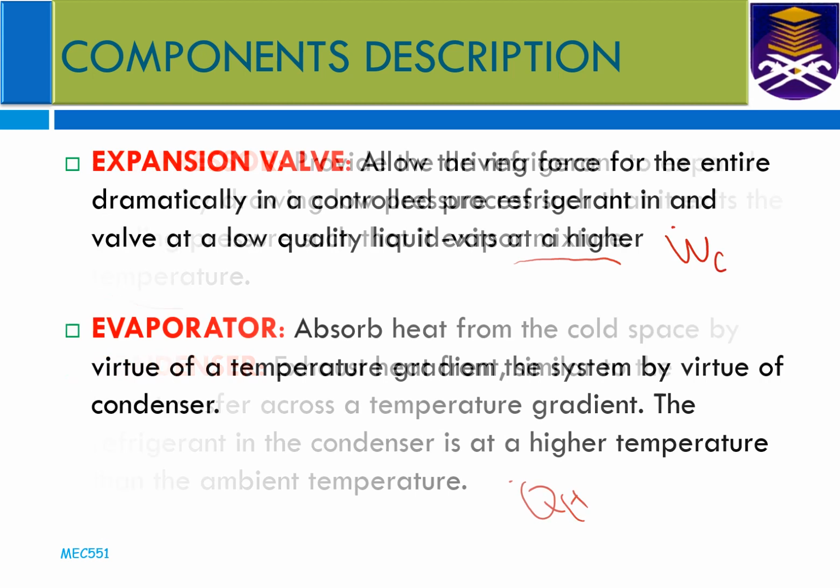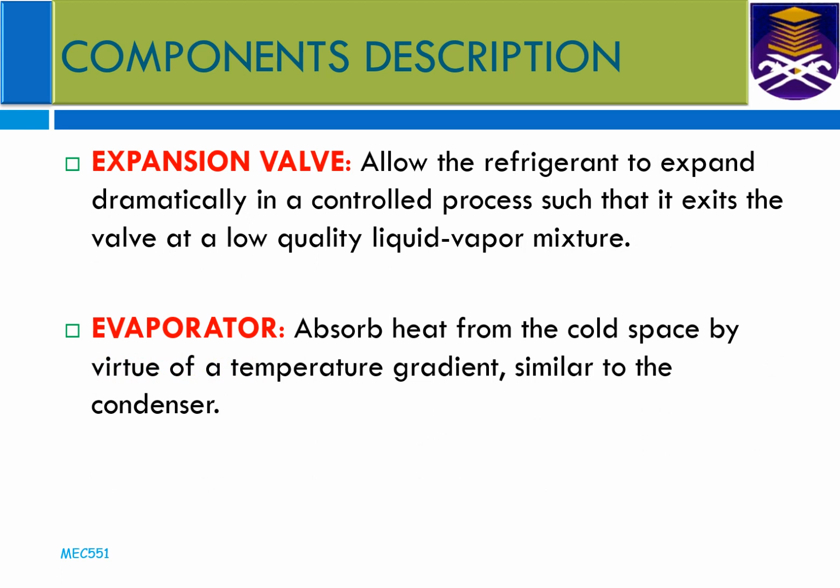Okay, and then the expansion valve allows the refrigerant to expand in a controlled process such that it will exit the valve with low quality in the liquid-vapor region. So there is no power input in the expansion valve, thus the W dot is equal to 0.